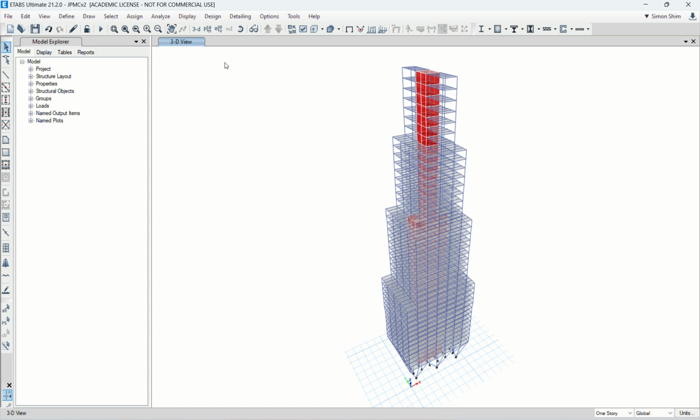That means we simplify so that any node within this diaphragm moves together. So obviously this plate moves globally together in X, Y, and rotation. We don't really consider any intermediate displacement within this slab.